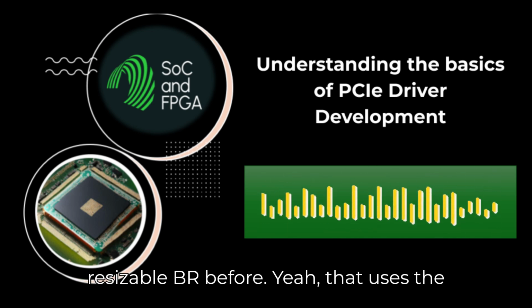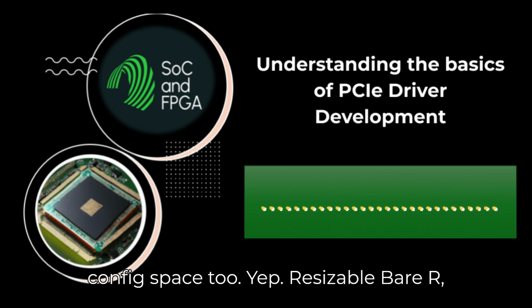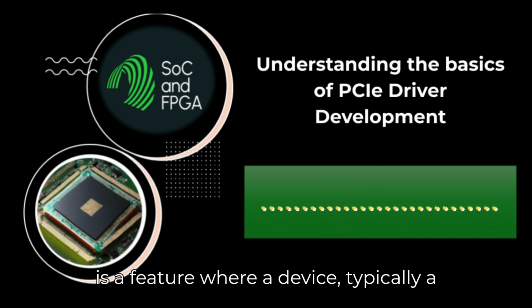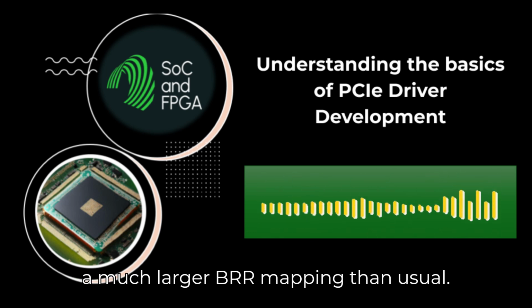And you mentioned resizable BAR before. That uses the config space too. Yep. Resizable BAR, or Smart Access Memory, as some call it, is a feature where a device, typically a GPU, can negotiate with the system to get a much larger BAR mapping than usual.